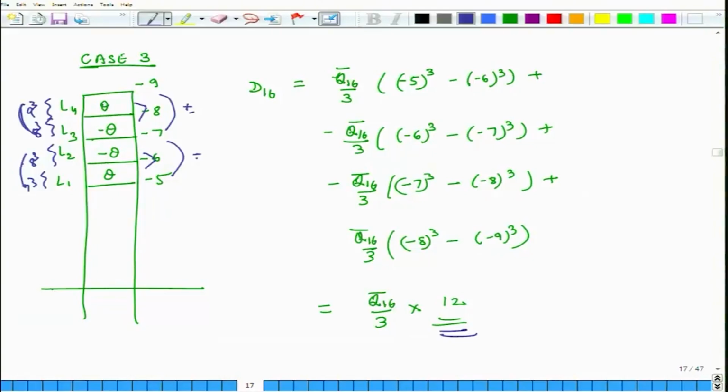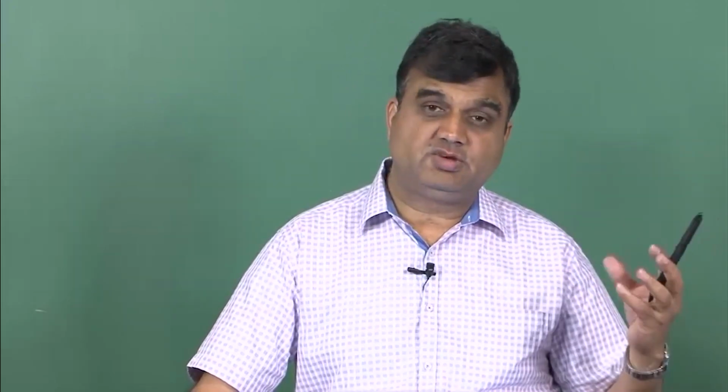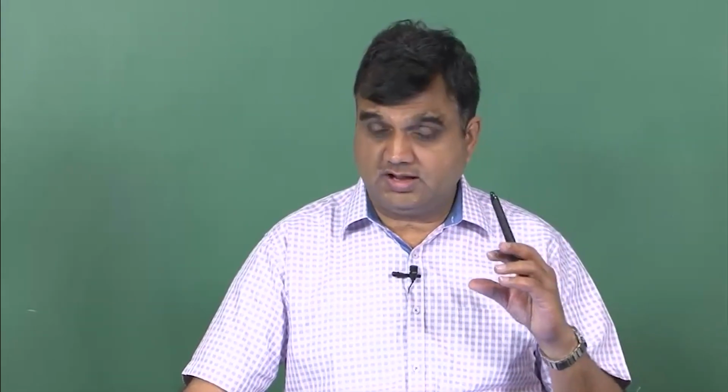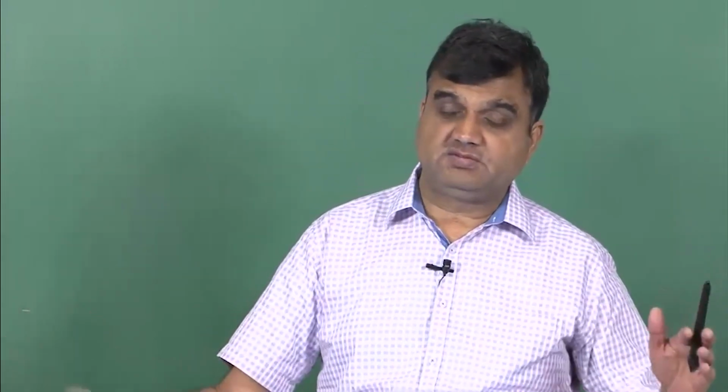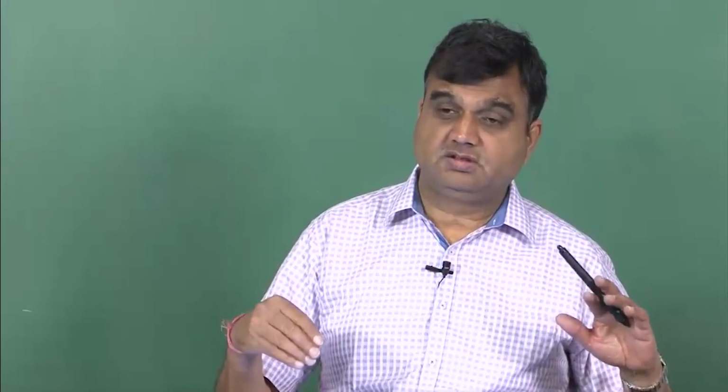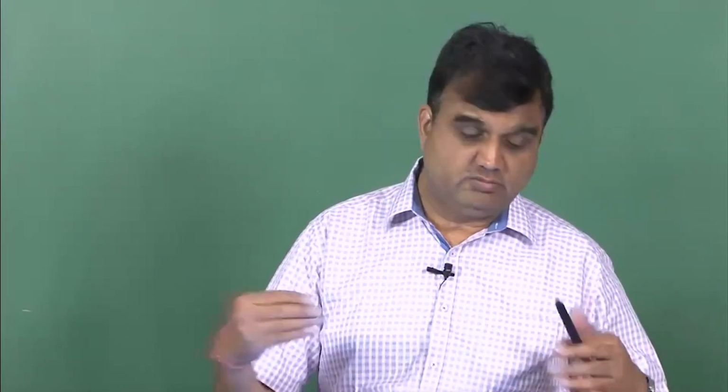We are also able to exactly ensure A16 and A26 is 0, and we can reduce D16 and D26 to a fairly small number, so that the coupling between bending and twisting is also minimized, not exactly made 0 or eliminated, but minimized. And in this way we have a system which behaves in the way we would like it to behave.